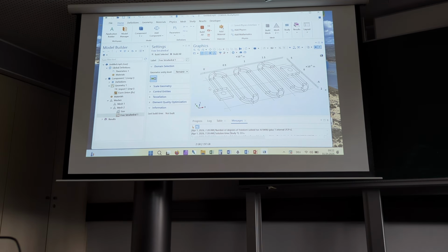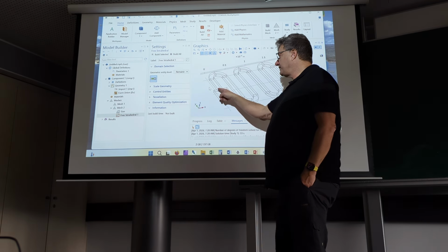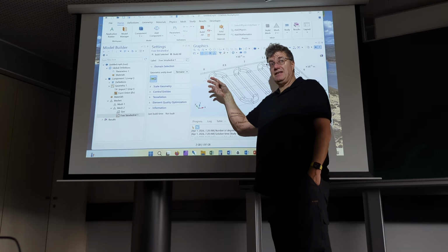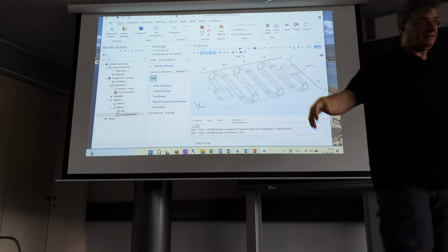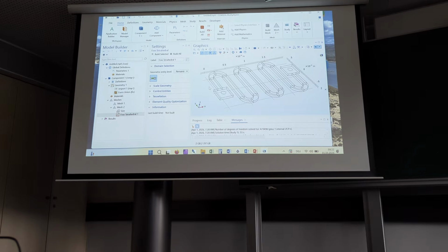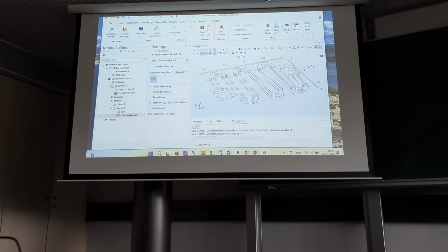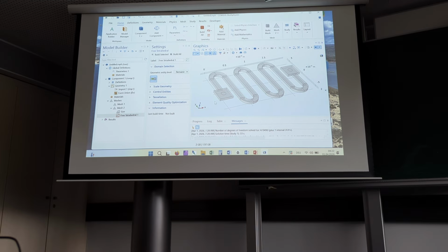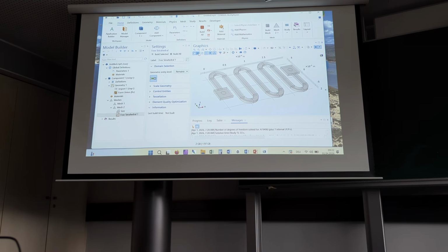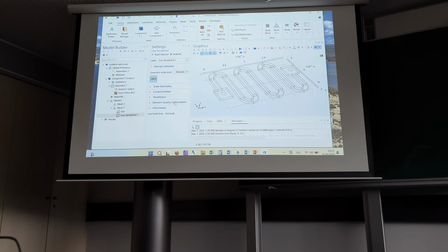What I want to do is to start meshing with that cross-section here, but that's an internal region I haven't even seen before when I had this different display. So sometimes if you need to look inside the structure, it's a good idea to use wireframe. You see, otherwise you don't even see it. An alternative would be transparency that also allows you to look inside. Maybe it's even more clear if I go to wireframe.